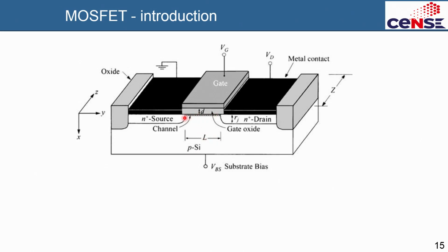here. As soon as the channel inverts, when you apply a strong positive gate voltage, your channel forms here, as we have discussed in the last few lectures in a MOS capacitor. This channel will form here because of strong inversion, if you recall. Now this is N plus, this is a high density of electrons, this is again N plus. So you see from here to here you have a path. N plus source can talk to N plus drain. That means there will be a very high current that goes through this channel of high density electrons that is